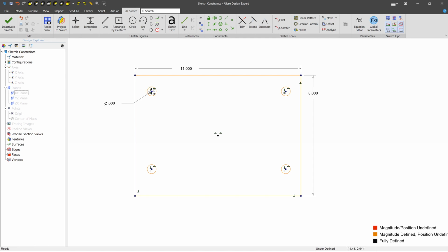The other thing we need to do is to figure out the offset from the sides. So we'll say maybe this is an offset of 0.8. And maybe from the top, it's 0.8. We can see that when we do that, some other things have happened. This one has moved also, and this one has moved to the left. So we have to create a few more dimensions.